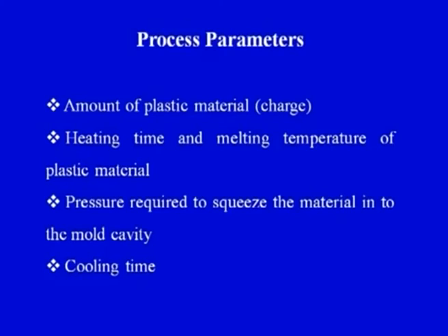Third, the pressure required to squeeze the material into the mold cavity. The mold cavity is generated between the upper movable mold half and the lower fixed mold half. Within that mold cavity, how much pressure is required so that the molten plastic is able to fill each and every corner of the mold cavity. So the pressure required to squeeze the material into the mold cavity is equally important.